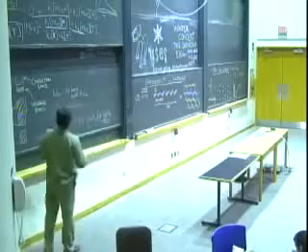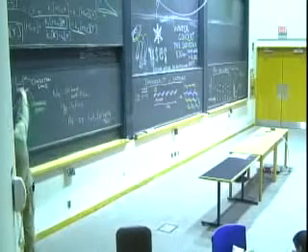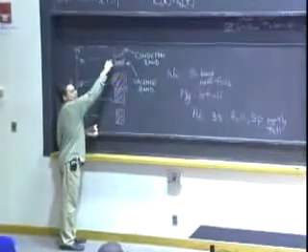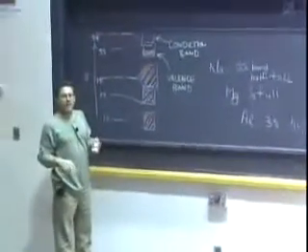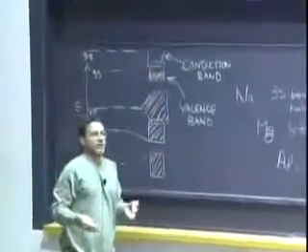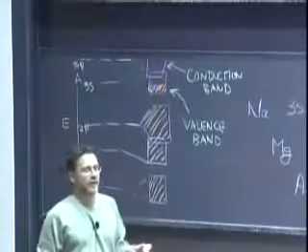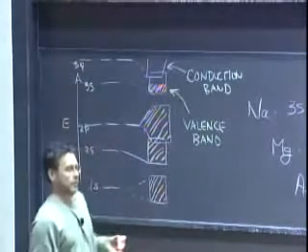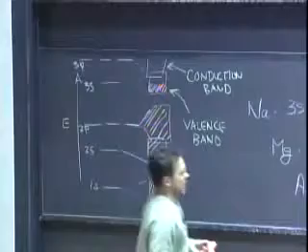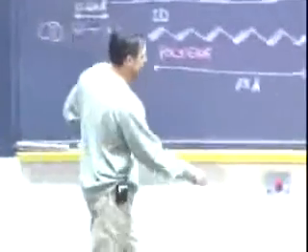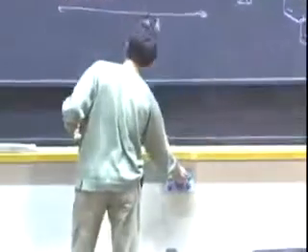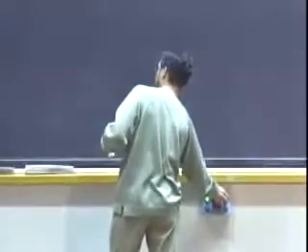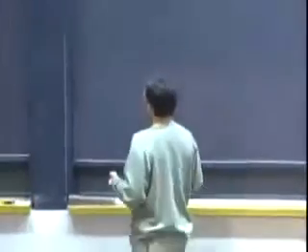And it's a consequence of the fact that the electrons in the valence band are right here at the same energy as the lowest part of the conduction band in a metal that gives metals their luster. It gives them their 100% optical reflectivity, these properties that we very much associate with metals. And so from analyzing band structure diagrams, even simplified ones, like the ones you'll find here and in your textbook today, you can really say a lot about the properties of different materials.